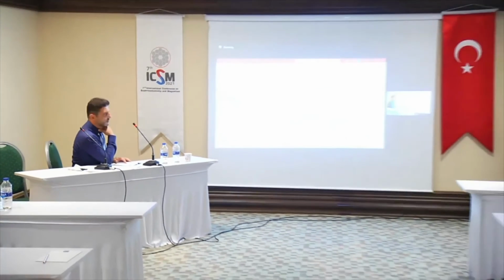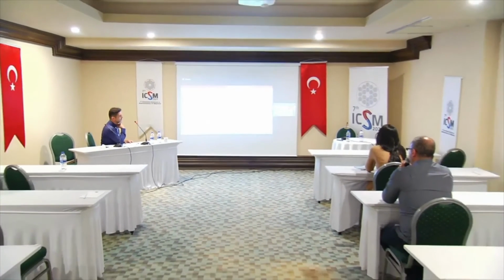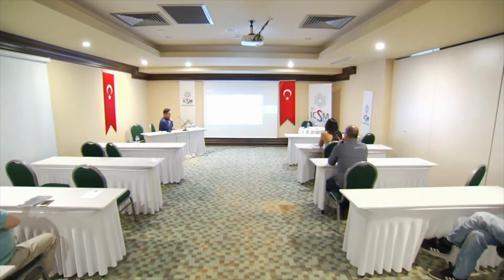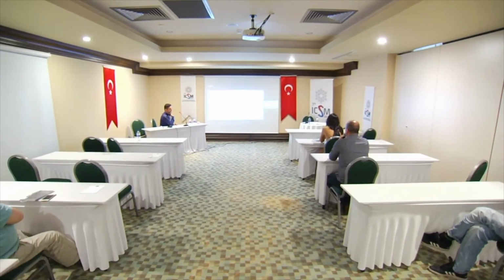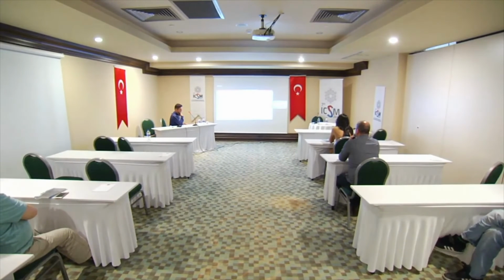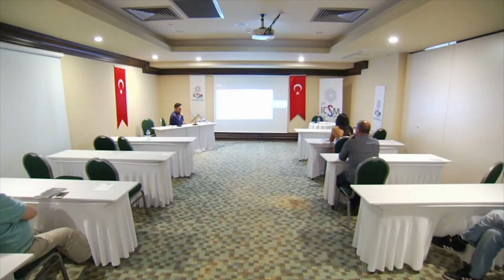I have one question. The shielding concerns the DC magnetic field, I guess. So for the modeling using the A-V formulation and the H formulation, in this case it's clear that the A-V formulation will be more efficient because the H formulation is mostly dynamic, is more suitable for dynamic cases. I don't know if my question is clear. Why do you make such a comparison?